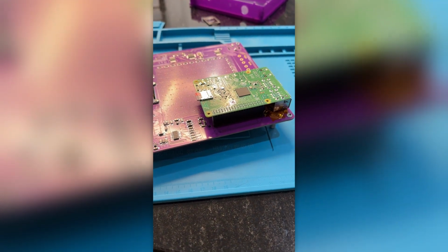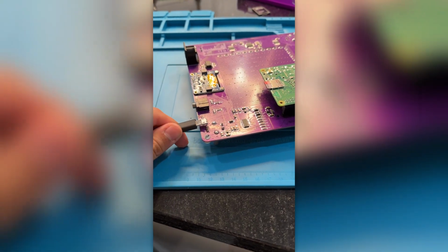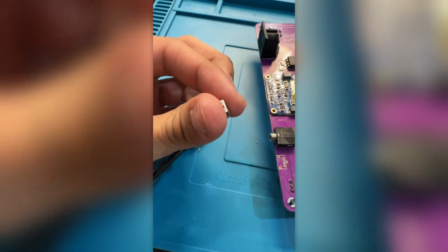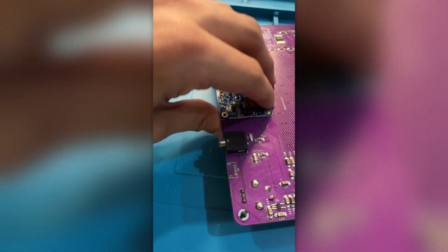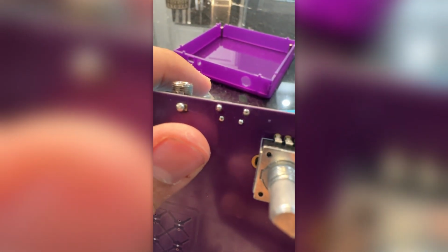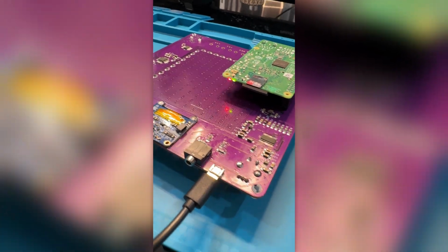So I go to plug in the power for the first time, get all excited, and whomp, the thing snapped off instantly, because that was one of the things I first soldered on when I didn't know jack about how to solder. Oh, yep, just fell right off. Here, let me flip the board over. You can see the solder is still there. That's how cold it was. The solder's on the board, but it's not touching the pins at all. I resoldered it. We got power to the board.